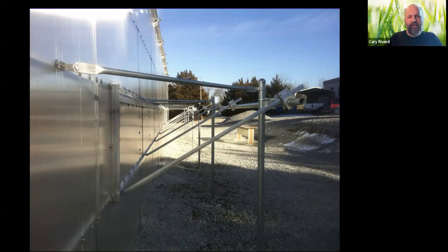And one of the things that's nice about rigid vents too is because they're typically much larger than a louver or a shutter, we can open that vent up and not turn on a fan on a cold day, and it's going to really slowly cool off the greenhouse. You should have some circulation fans in there anyways that are going to help draw in some of that cool air. So typically, in the wintertime, it's not uncommon in our greenhouse for this rigid vent to open up, cool off the greenhouse, and then just close again, and it never turns on the suction fan or the ventilation fan because it's large enough that a fair bit of cool air can just slowly make its way in.